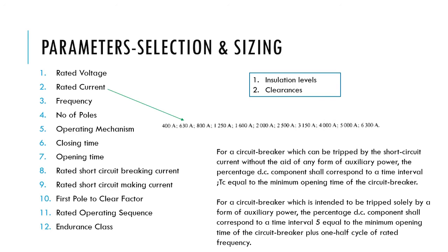These exist only for a few seconds, not even seconds. It is just a tree branch hitting the conductor and going away. It comes, connects to my phase and goes, so it's a temporary fault. For this, I should not interrupt the entire system.